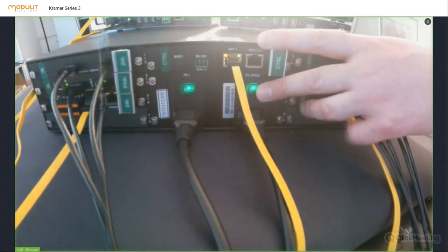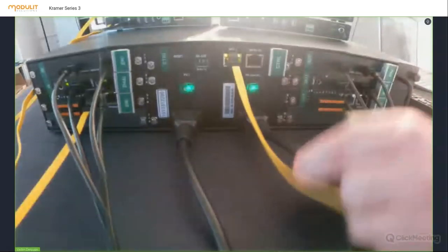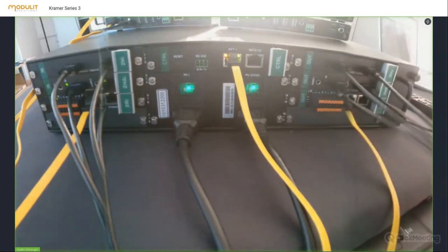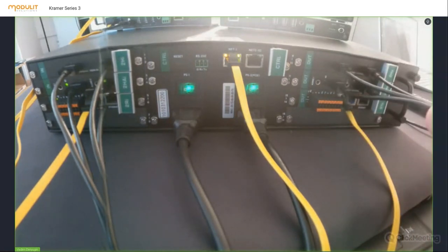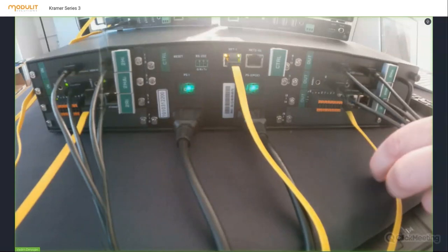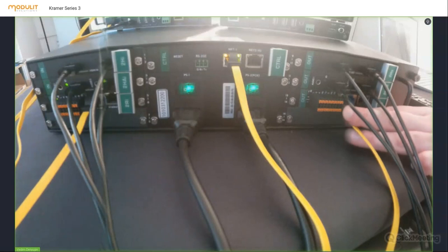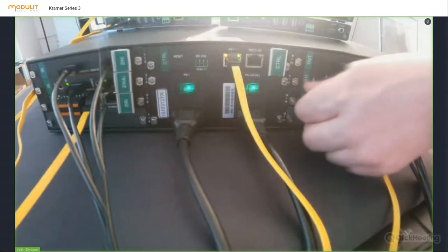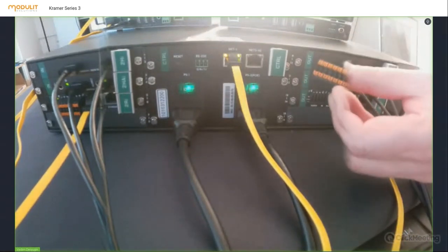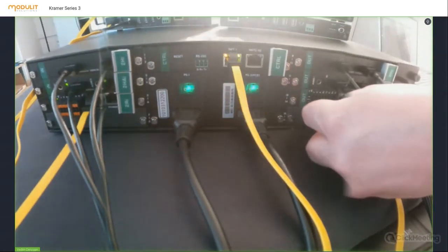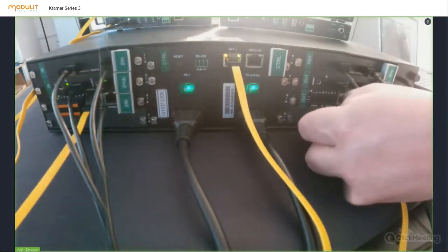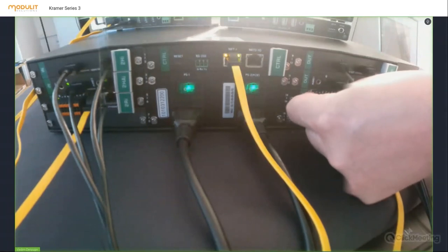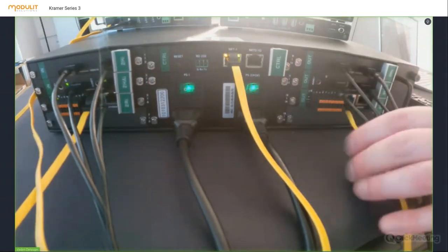HDBaseT cards, then you'll be using the second power cable in order to provide the HDBaseT PoE to power your external devices. We are using four output HDMIs to connect our video wall that's located behind me. I will show it to you a little bit later. And also we are having one more HDBaseT output here. We also have some quick connect terminals here to connect the audio and RS-232 to be sent via the HDBaseT. That's it. It connects pretty fast, and it's really convenient to use.